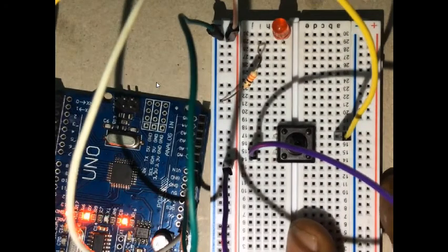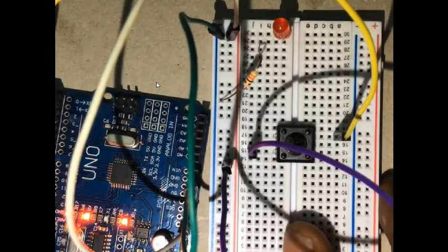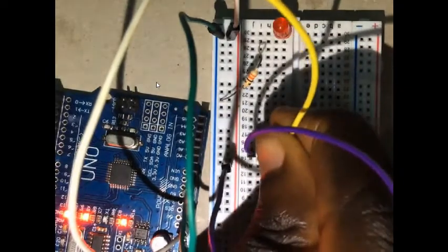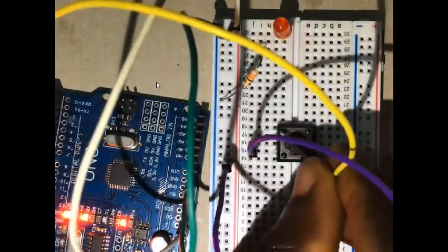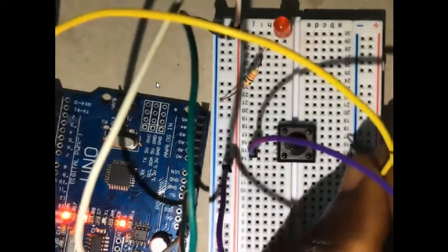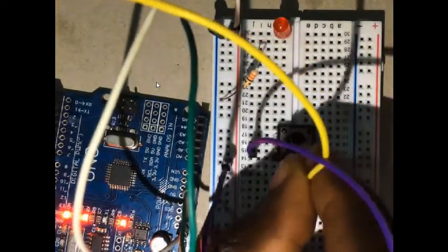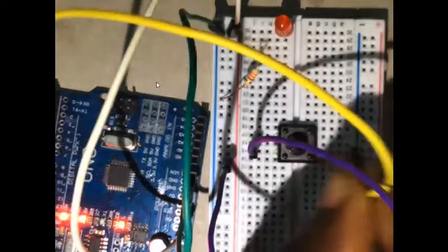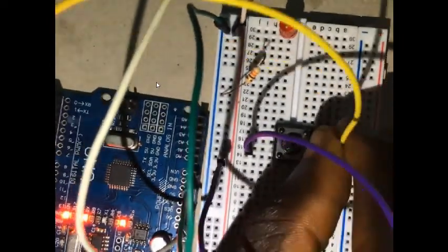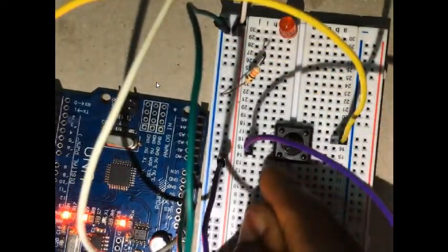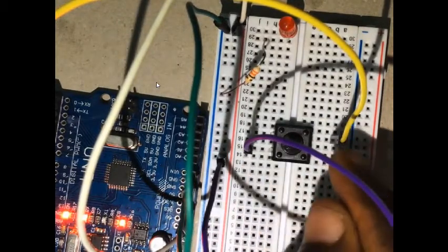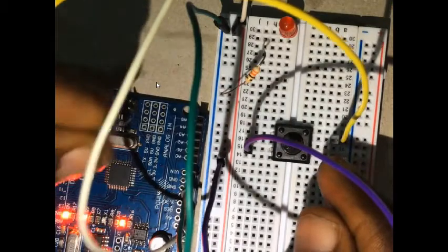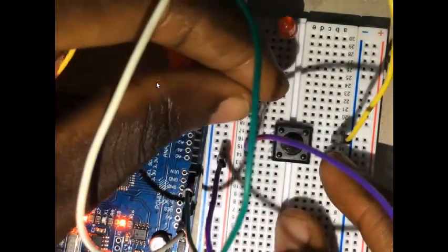So we usually connect this lead of the button. You know, this is electrically connected together with this side. So the whole of line 17 now is electrically connected together. So we usually connect the line or the part of the button that is also connected to the digital pin with a resistor to ground.